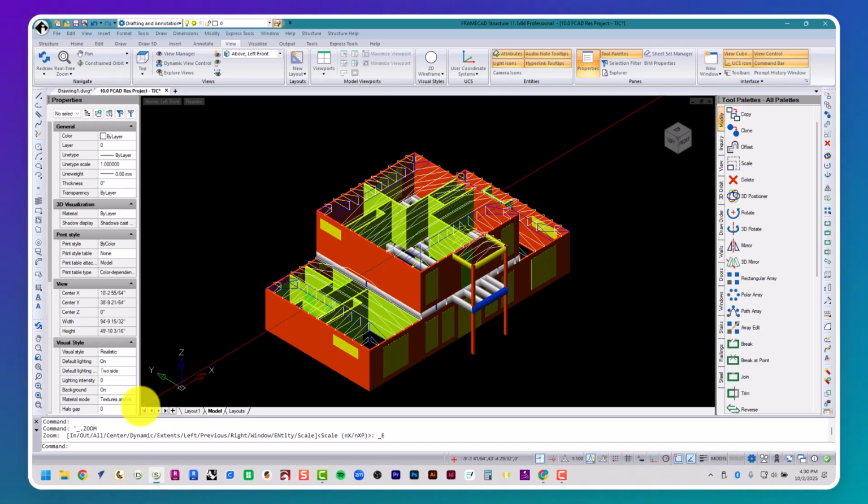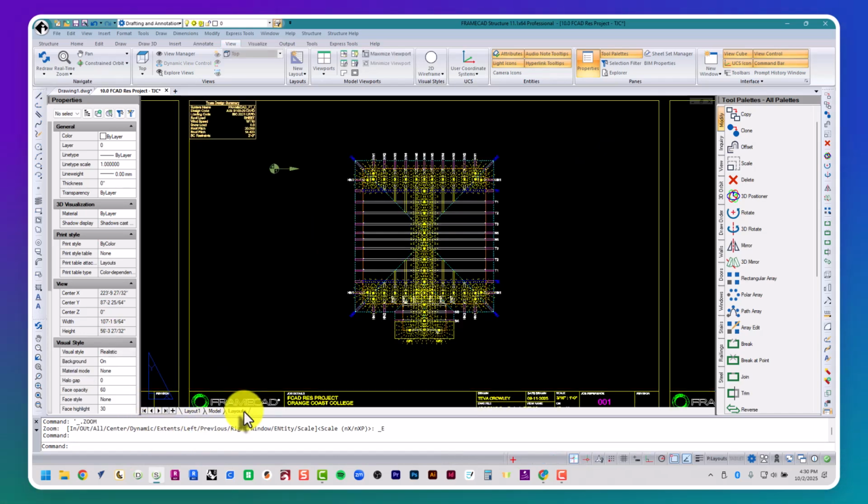which have their own openings. And then we can move down to the floor system once we have a definitive idea of the second floor walls and upper roof trusses, and so on and so forth. So when it comes to building and structure, we start at the very top and progressively work our way to the bottom. We're going to start by moving our upper roof trusses from border number 6 to border number 5.